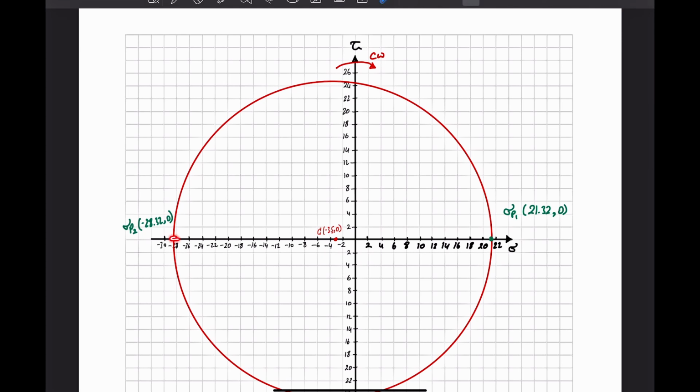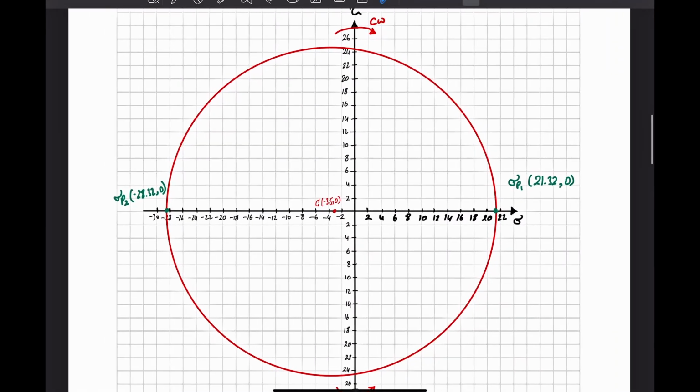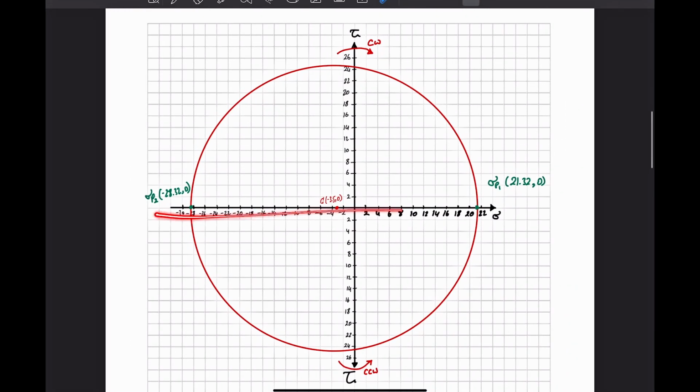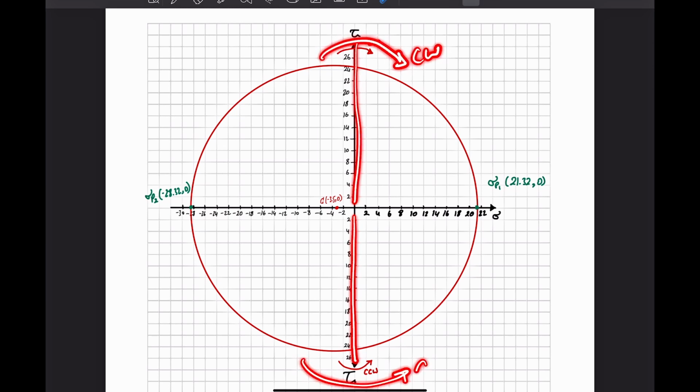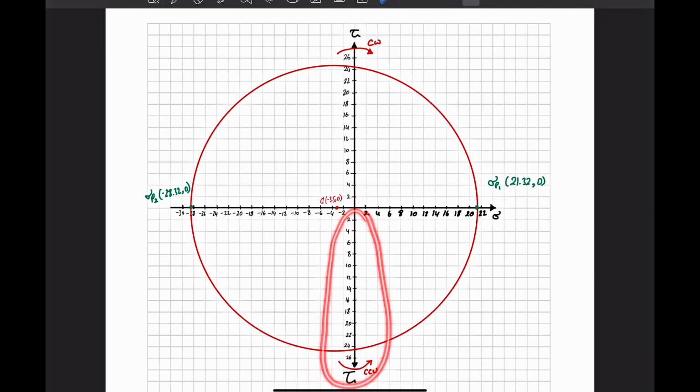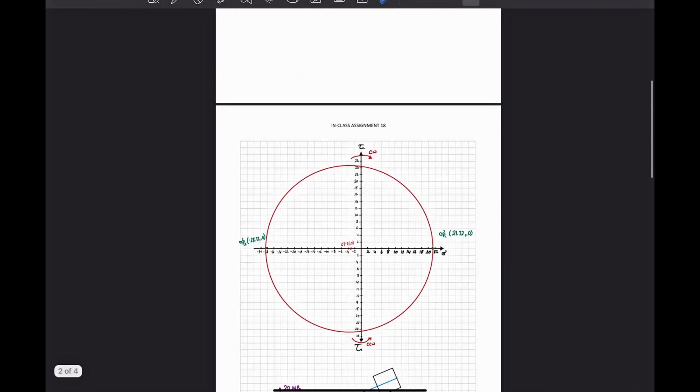So once you know the boundary of the circle, that's when you can establish the horizontal and vertical scale. So what were we drawing the Mohr circle on? We are drawing on sigma and then tau. And if you remember, we're not calling tau positive and tau negative. Instead, we are calling clockwise tau, and here counterclockwise tau. So as if this side, which is supposed to be negative, we are not calling it negative, we are calling it counterclockwise, and we're drawing it like this. So it's always gonna be that way.